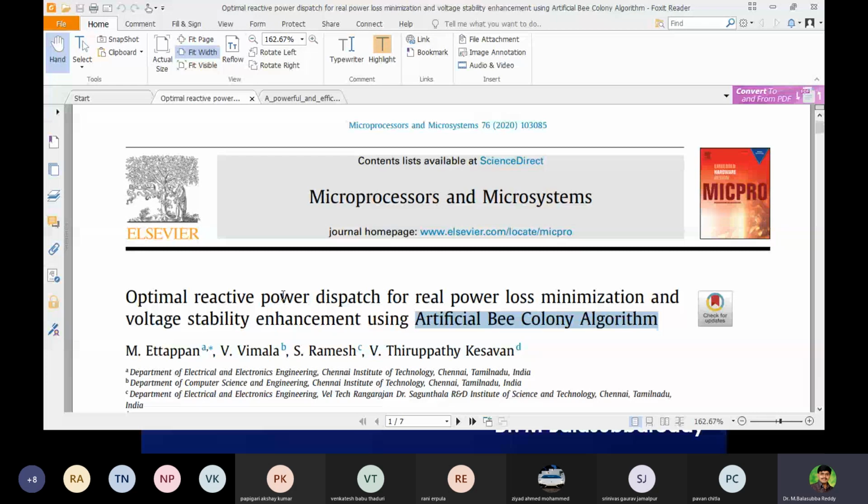You take it as a loss function. As you are aware, in a power system, even in Newton-Raphson and so on, we find the total system loss. How will you find the system loss? I think you recall in the Newton-Raphson method, the line flows, the current or power flows from bus 1 to bus 2 and bus 2 to bus 1. Like that, if you calculate all the bus line flows and sum them, whatever value you get is nothing but the power loss in the system.